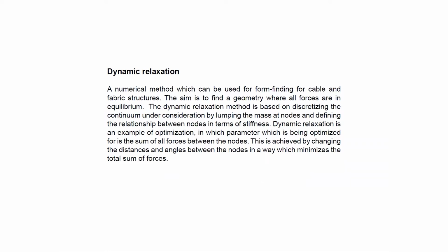So yeah, dynamic relaxation is basically a form finding method. Also, we are trying to find minimal surfaces or some surface configuration. Okay, and we assume that there are certain forces that run through this surface. Okay, and these forces, because they're vector quantities, of course they act on the nodes on the surface. So the surface is discretized; it has nodes.